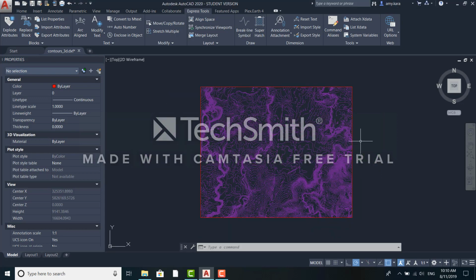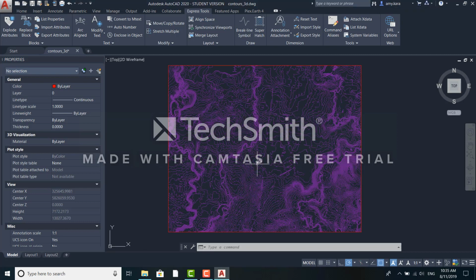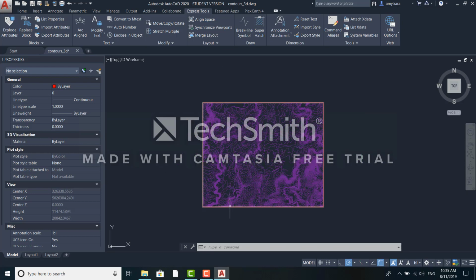Okay, so now I've got the contours trimmed to be all inside this boundary rectangle. The next thing we're going to do is to create a new UCS, which is a new origin point for the X and Y. This will allow 3ds Max to cope a bit better with the contours in order to create a terrain, as right now it is in its world origin point, and that will be quite far away from the 3ds Max origin point.